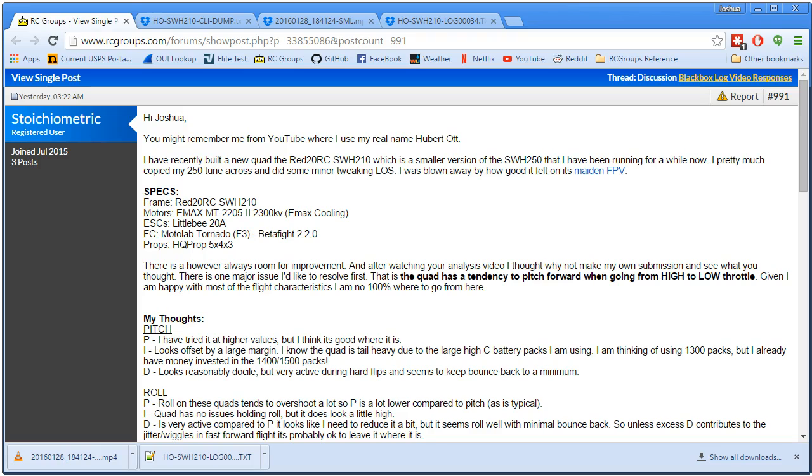But what we do know is that the I term is positive in forward flight, meaning a pitch forward moment counteracting a persistent pitch back force, and that moving the CG of the copter, at least in my experience, has a minimal effect. So, it's probably aerodynamic is my conclusion. The PID loop has to be able to respond fast enough to throttle changes, because the degree to which this effect is active changes depending on how fast you are flying, how far forward you are pitched.